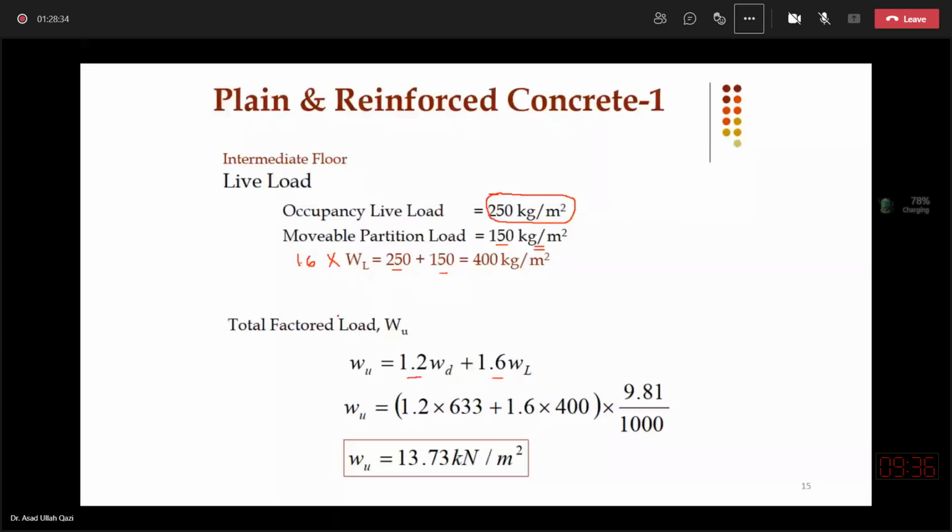It is normally decided based on the type of the building how much alteration or variation they are going to make, and whether the partitions will remain the same lightweight ones, or they may altogether change the type of partition. So normally exact drawings are required, and the location of the walls, type, thickness, and height are known, and then using the densities we can calculate the load of total additional walls, which are although non-load bearing,